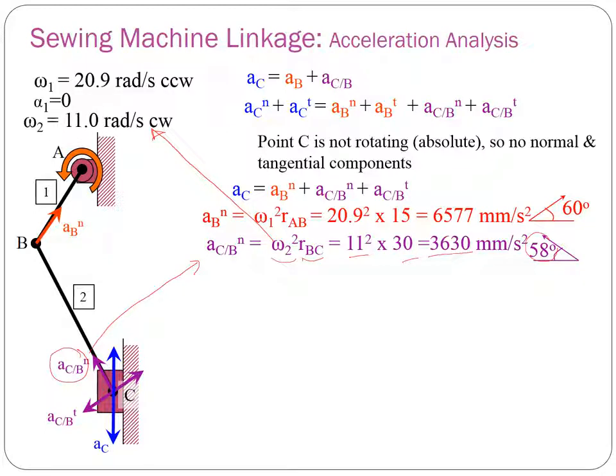So how do you get this angle? Okay, you have drawn the whole kinematic diagram. You should be able to measure what would be the angle here using the compass. Sorry, protractor, not compass. You can use a protractor to measure the angle here.